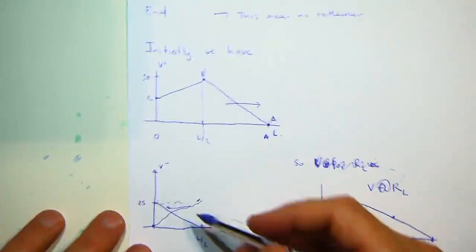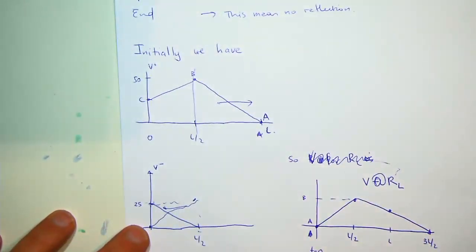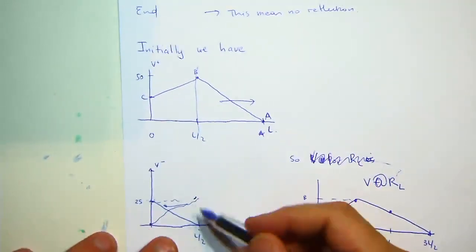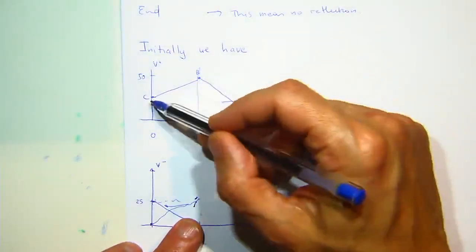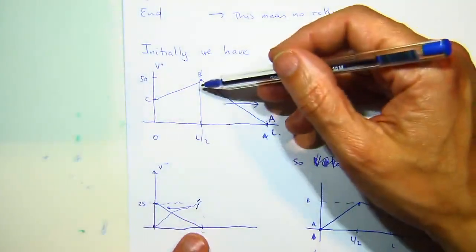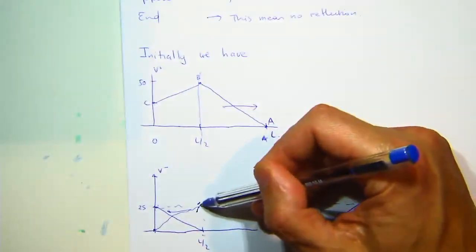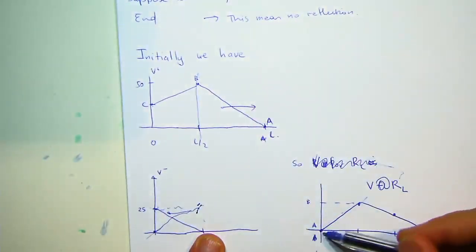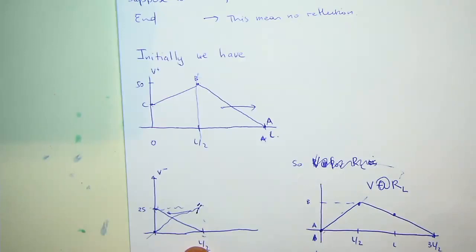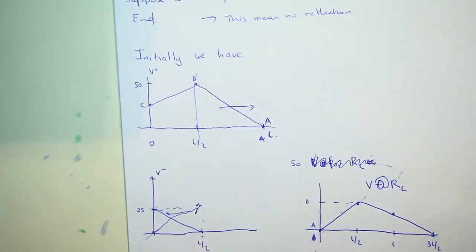So this has reflected, it's open circuit, so gamma is +1. All of a sudden it's flipping, and so for this section between these two, when they start arriving at the load, you're going to start getting this joining up to this, and you're going to start seeing that segment through the load. That's all I'm saying. So you're going to get a different resulting pattern through the load, which is the combination of the positive going signal that was going through the load plus the signal that was reflected, came back to you, and then makes itself through the load. And that's what the load's going to see.